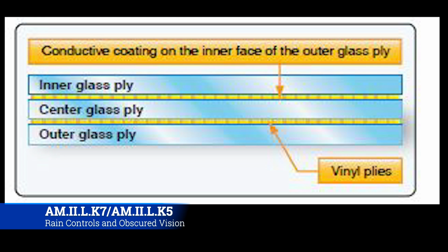But effectively, you have these different plexiglass plies with either wires that are very, very thin, or a conductive material of some variety that's usually clear. They put it all together and then pressurize it, like a sandwich structure that you squeeze together super hard, and it makes it into one piece. And then it gets installed on the aircraft.